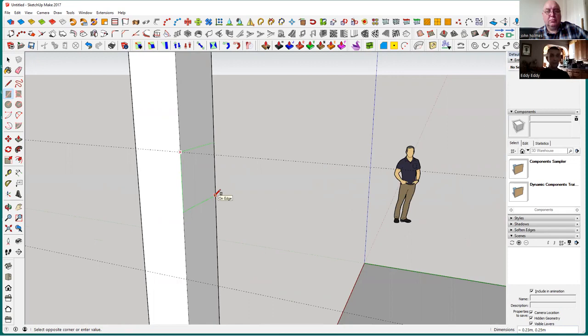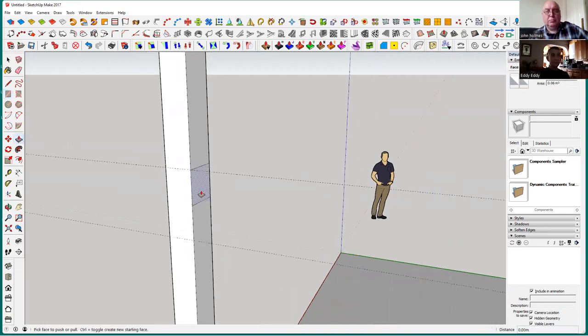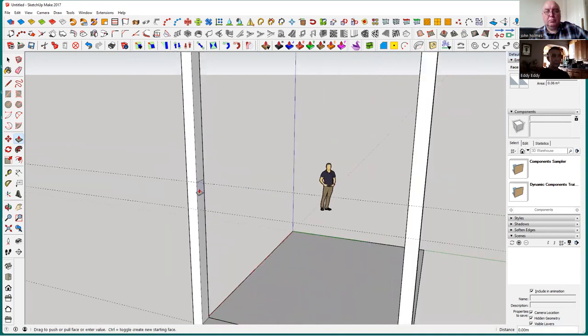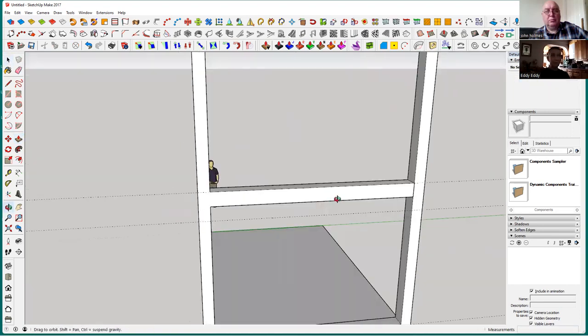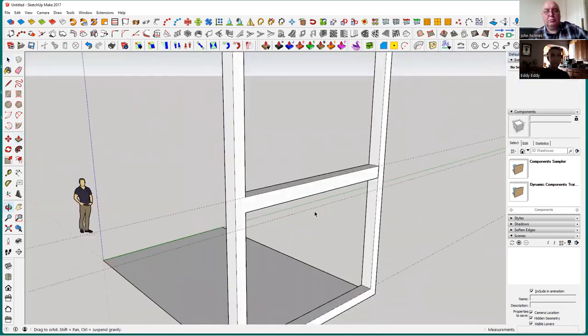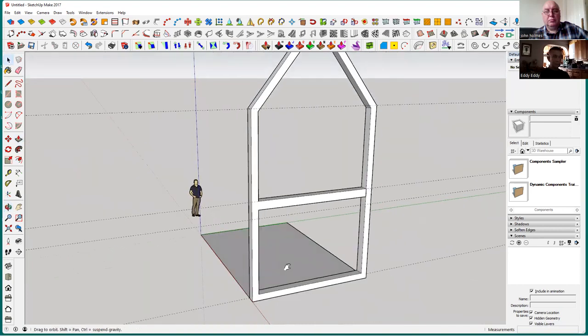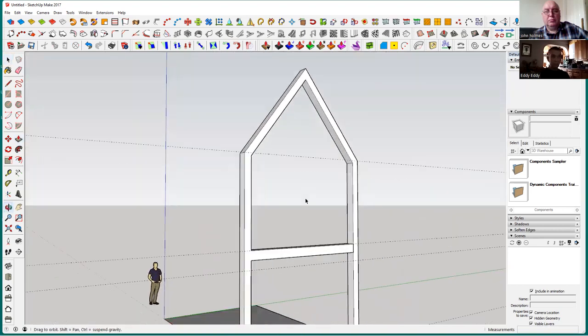And in the right-hand corner, it's giving you the size. So really, we want 0.25, where it says by 0.25, enter. Click. And then we use the push-pull tool again. Pull it across to the other side, and that's where we can balance our floor. So we're good for a floor. So it's end wall and floor.